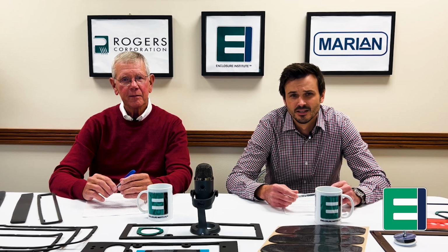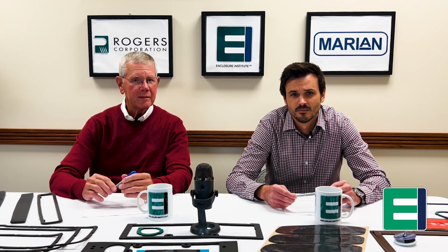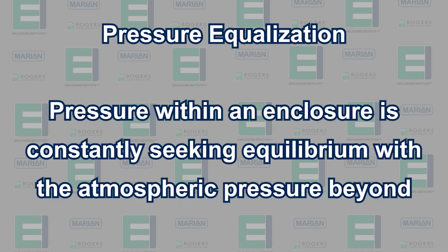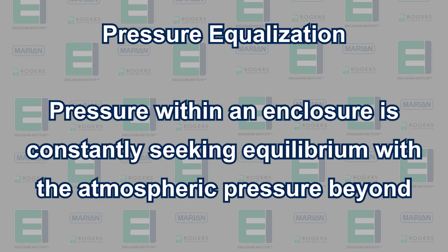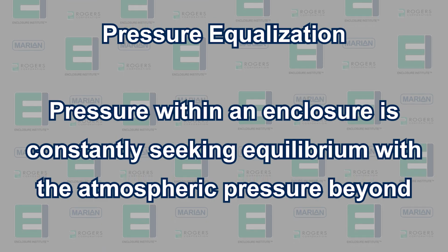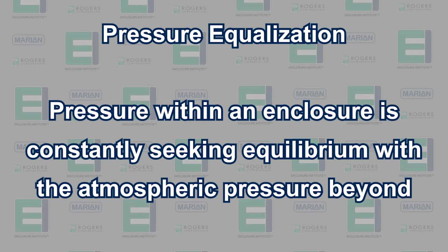But the need for ventilation goes beyond simply heat or temperature relief. The increase in temperature is accompanied by an increase in the internal pressure and the buildup of moisture in warm air. A proper vent will, first of all, allow for pressure equalization. Atmospheric pressures are constantly changing. The pressure within an enclosure is constantly seeking equilibrium with the atmospheric pressure beyond.